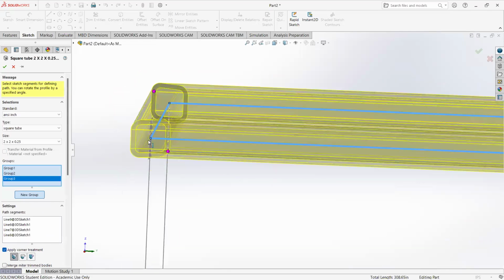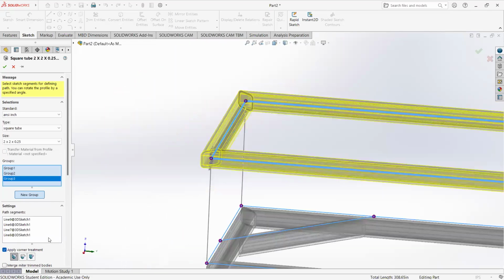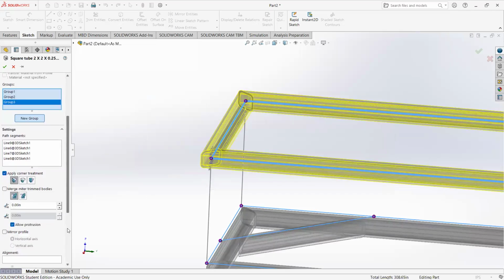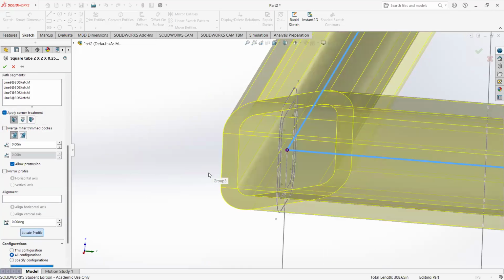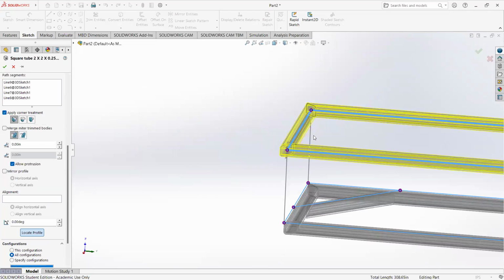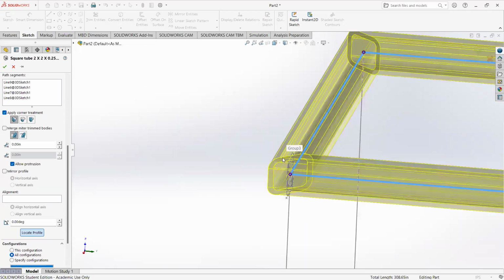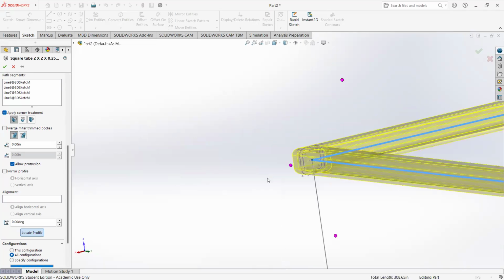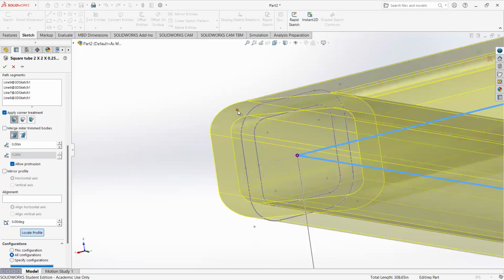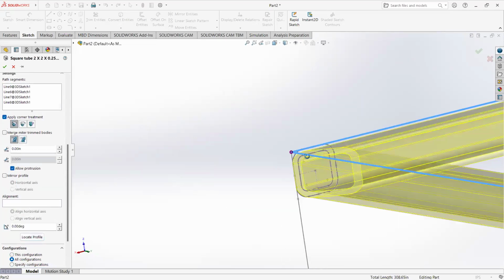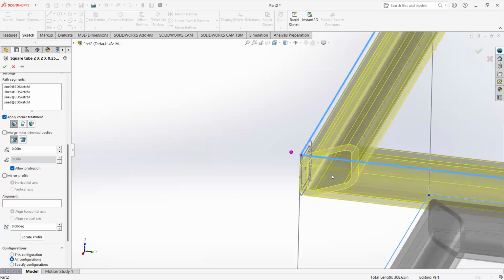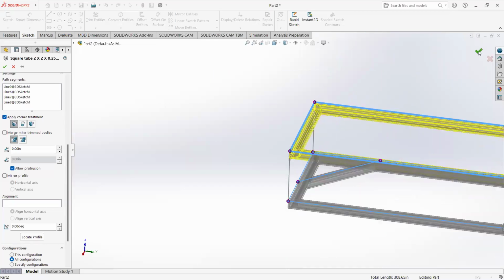And notice again, I'm centered. I'm going to locate my profile. So locate profile. And in this case, I want it to be below and inside that top. So I've got the outer dimension and the top. Now, where is my sketch? The sketch is here, so it's going to be that point out in space. And now I'm below and inside my profile.